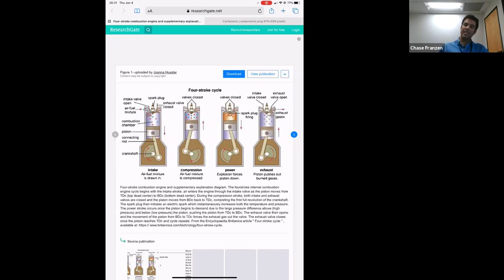And again, if you compress fuel and air down, and if it's really, really hot, you can have a pre-ignition condition. So that's why we like to look at our cylinder head temps, and if those cylinder head temps get hot enough, we can actually create a condition where the power stroke fires before the spark plug fires. And as you might imagine, because these are all interconnected, that screws things up. You have a partial loss of power. So that's really the power plant.